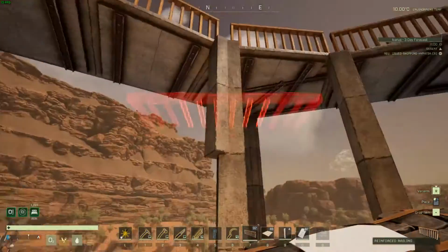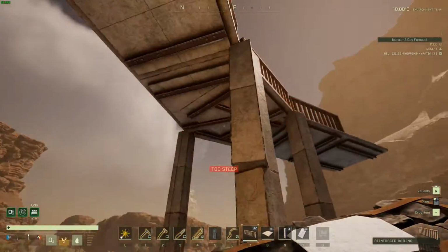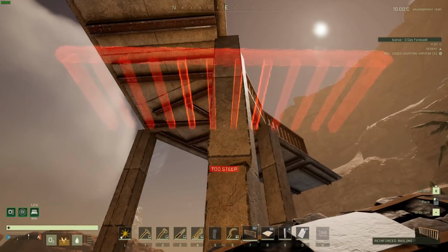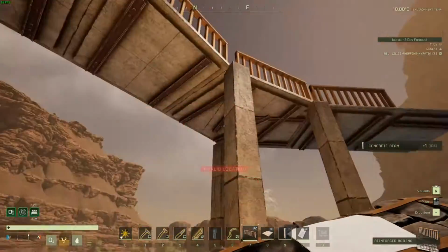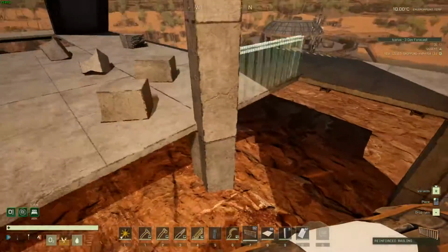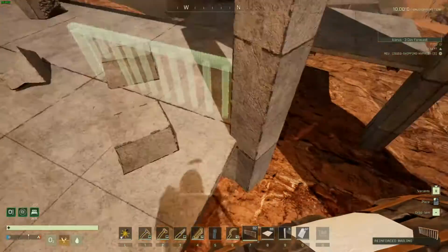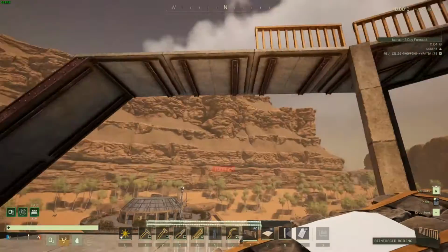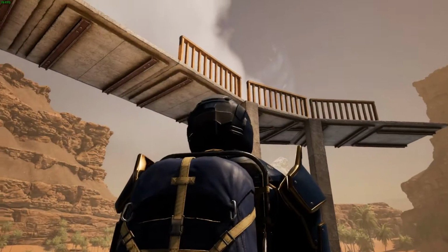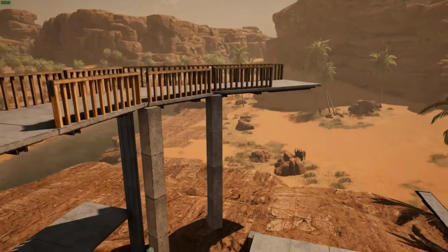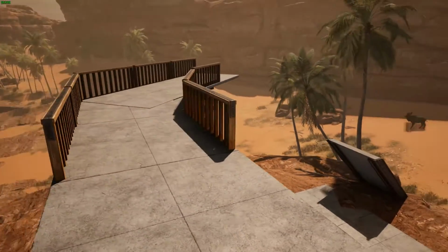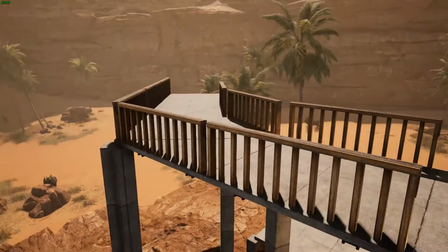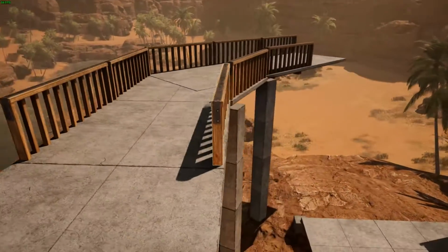So we got that vertical going all the way up. We don't need this one here anymore because we already have support at that spot over there. So we can get rid of this beam. Just have those guys there. We can leave the 90 down below here just because it's supporting our lower floor, right? But as you can see, this gives us a pretty good turn of a raised platform. That looks half decent from the railing on the inside and on the outside. So that's how you do that.